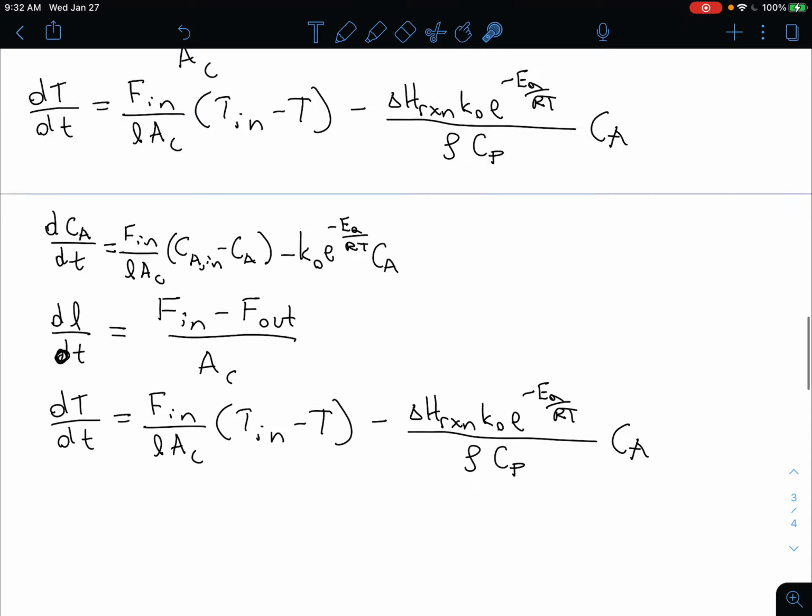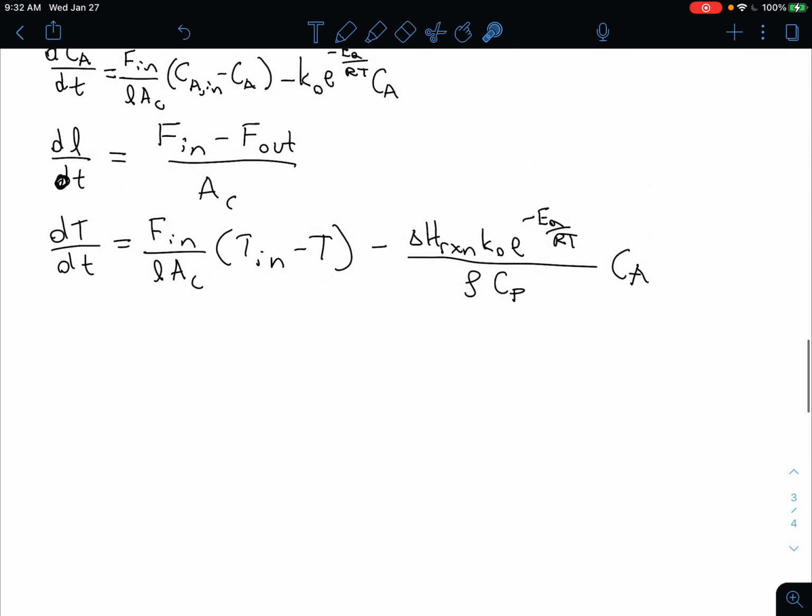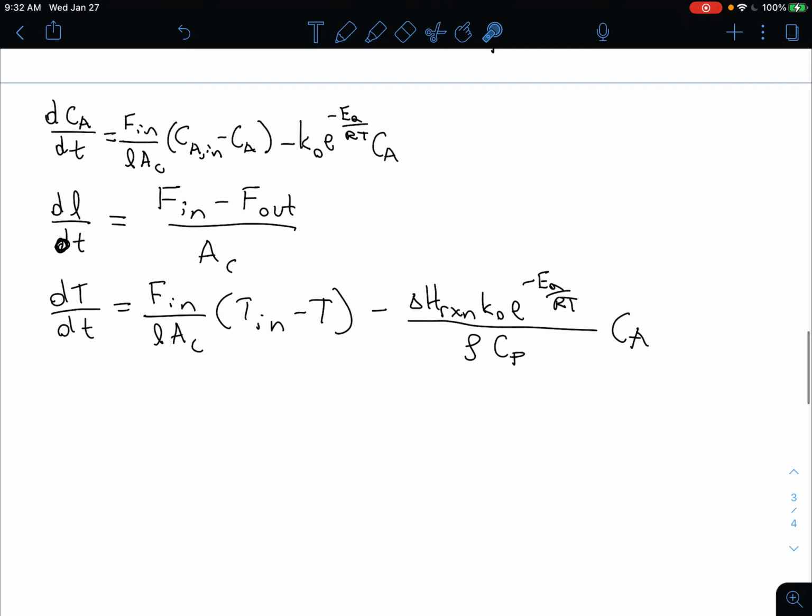Now one thing, we're not done with this video. For one thing, I promised you that I would discuss why this is 0. And I haven't done that, so I'll do that next. But also, we haven't really been too specific about CB. Because it's an irreversible reaction, the concentration of B does not explicitly show up in the equation for the concentration of A. It also doesn't show up in the equations for L or temperature. So in principle, we could calculate CA, L, and T without knowing CB, but nevertheless, if we wanted to know CB, we will have to do a balance on B.